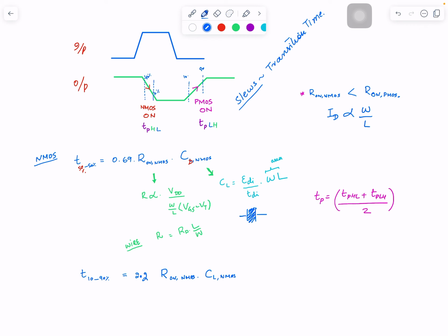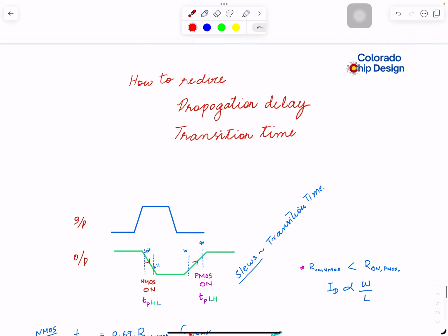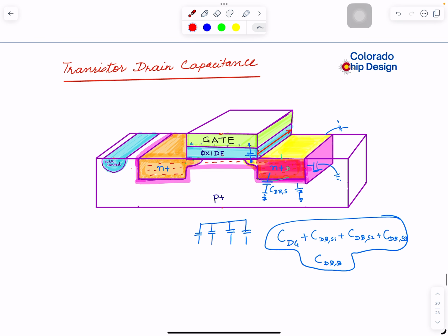If your thickness is larger, your capacitance is low. So in this case, if this is wider, capacitance will be smaller. So you need to make this thing wider, and you need to make these layers acting as a dielectric wider.